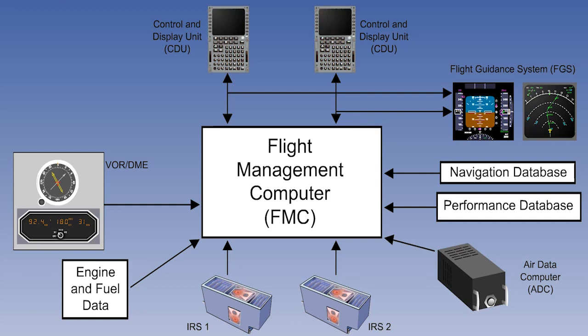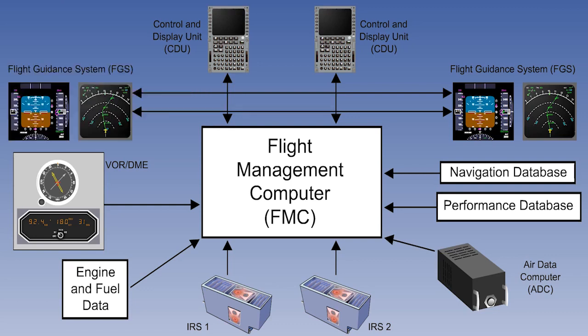This is a generic term which can either mean the flight director display on the electronic flight instrument system, or can mean the autopilot. This is the layout of an early model of the FMS fitted to the Boeing 737-400. And, although it did not have GPS, it was very similar to our basic model. You can see that there is one flight management computer serving both pilots and two inertial reference systems.